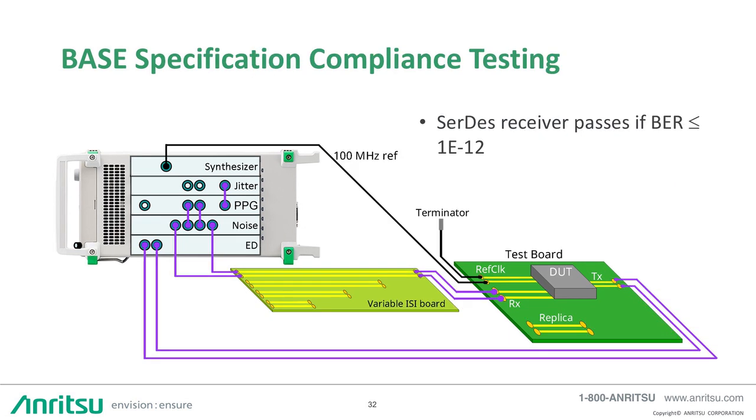The test setup is shown here for base testing. Notice that the 100 MHz reference clock is synthesized by the BERT. The DUT receiver must, of course, perform with a bit error rate of 1 in a trillion or better under the stressed eye conditions.